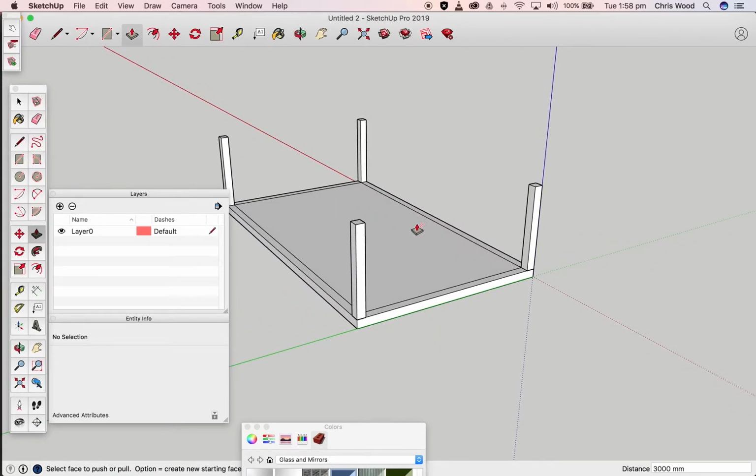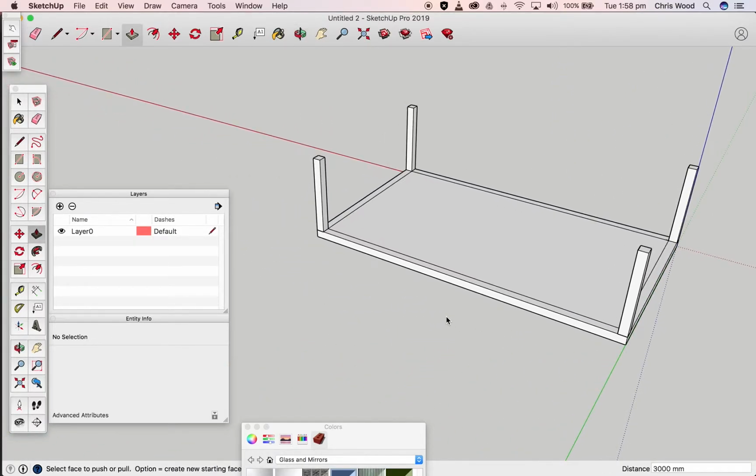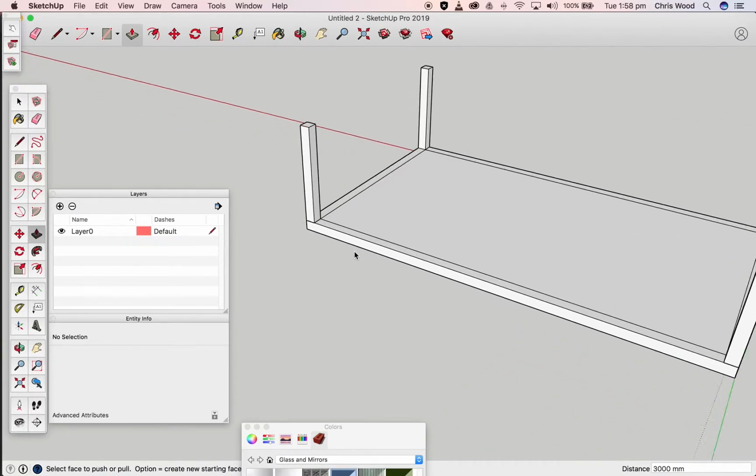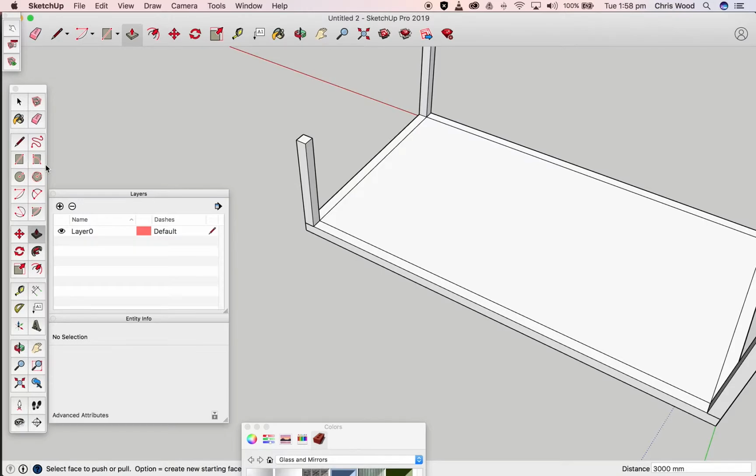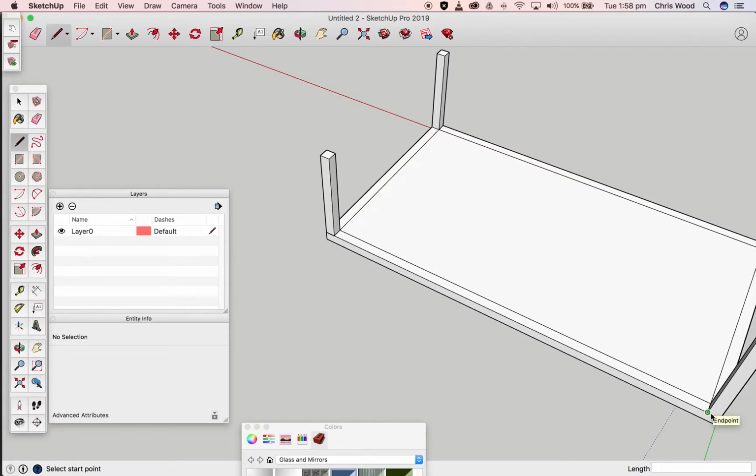I'm going to have steel beams running between these, but I'm also going to have some block wall and a combination of block wall and windows in between as well. So what I want to do is wherever I've got windows, I want to draw down a center line. I'm going to come down here and, let's have a look, I've got a total length of about 11,400. So I'm going to come in, let's say, 5,000. I'm just typing in the bottom there.